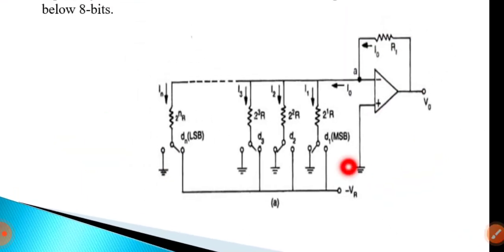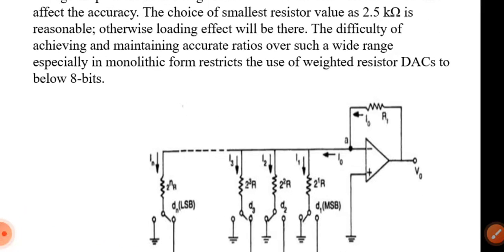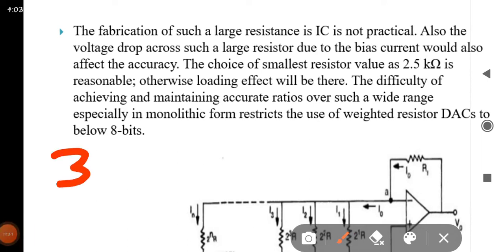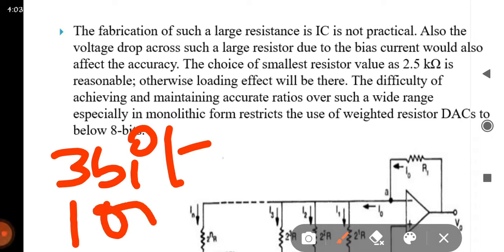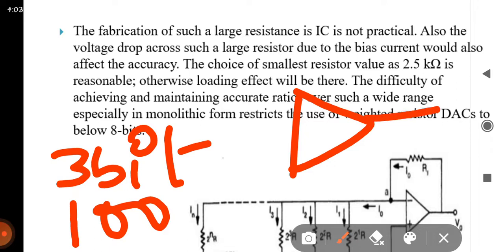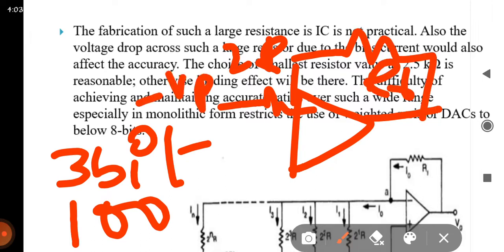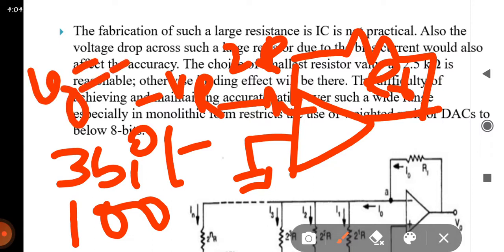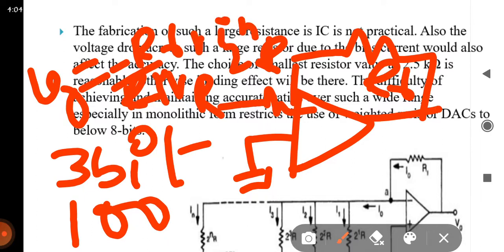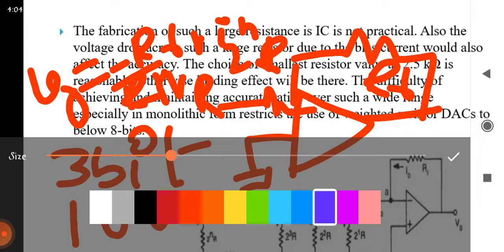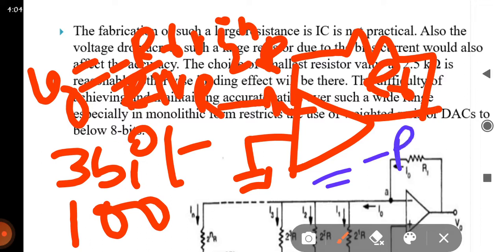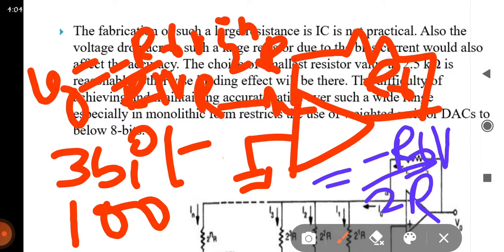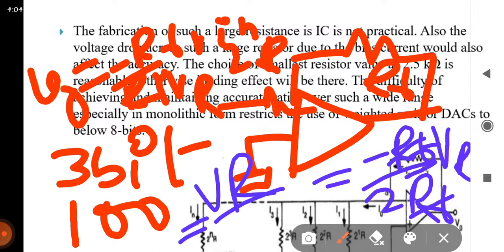I am going to take the negative input. I am going to take a 3-bit number, say 100. Can we write it? This is a 2R with the feedback RF and minus VR. This is ground. Yes, the output of the op amp is minus RF divided by RI into Vin. Instead of this, I take minus RF divided by 2R, into minus VR divided by RF. This one cancels. VR divided by 2 is the output for the 3-bit data.